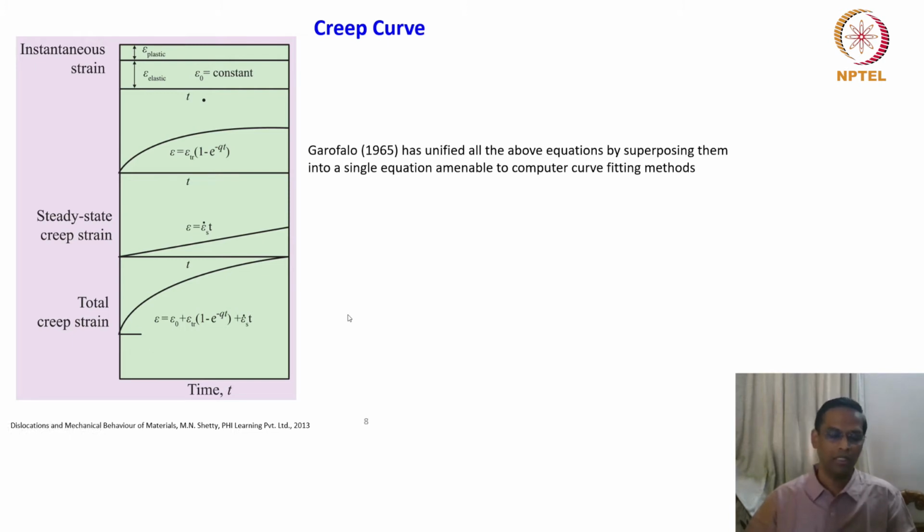Creep, as I just mentioned, is a strong function of stress, temperature and strain rate, and these are primary. But then there are whole other structural features which influence this. Each particular combination of stress, strain rate and temperature will drive each material class into different segments.